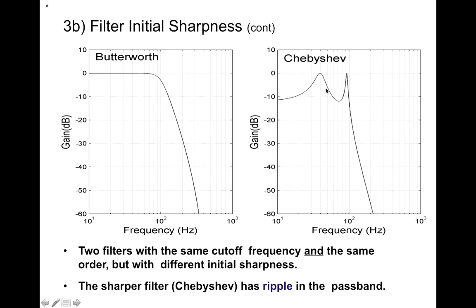Sometimes you're willing to live with this in order not to pick up any of this stuff and to have this rapid decay. And remember, it looks like this sort of gets bad out here, but remember that minus 20 dB is actually an order of magnitude cutoff. So if you were at 10 volts, then just in this little tiny space here, you've already reduced yourself to 10% of your original voltage.